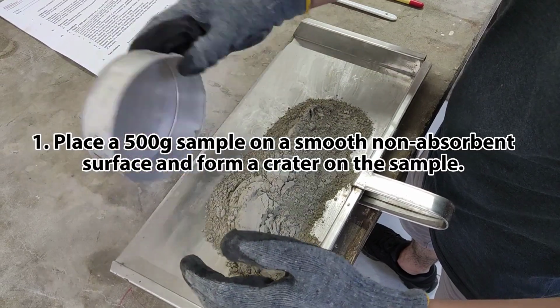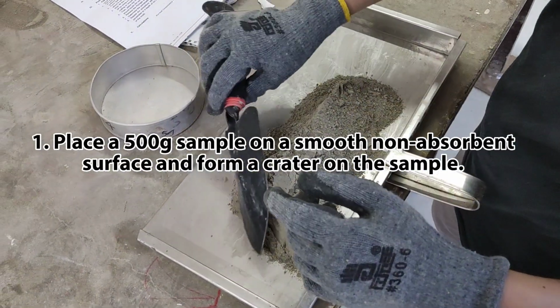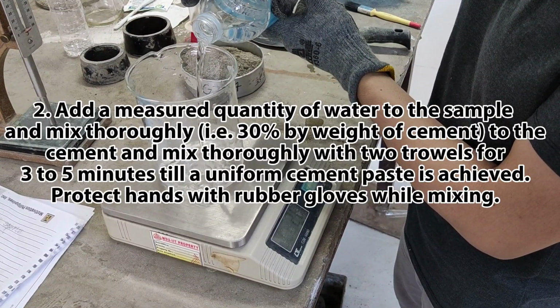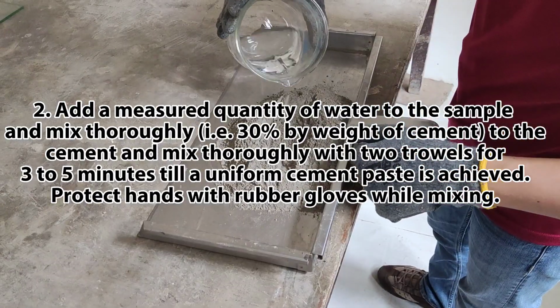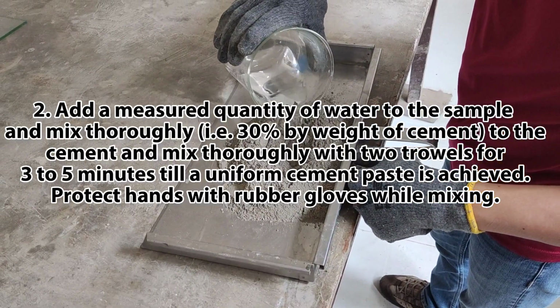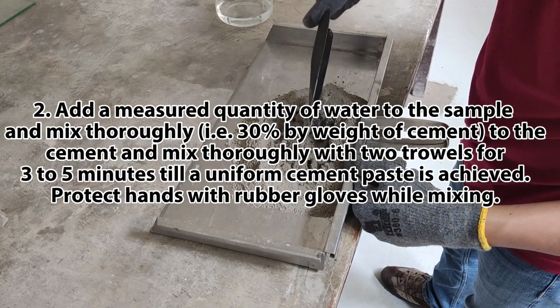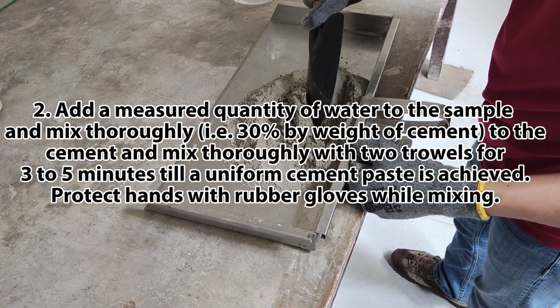First, place a 50-gram sample on a smooth non-absorbent surface and form a crater on the sample. Second, add a measured quantity of water to the sample and mix thoroughly. For example, 30% by the weight of the cement, and mix thoroughly with 2 trowels for 3 to 5 minutes till a uniform cement paste is achieved. Protect hands with rubber gloves while mixing.